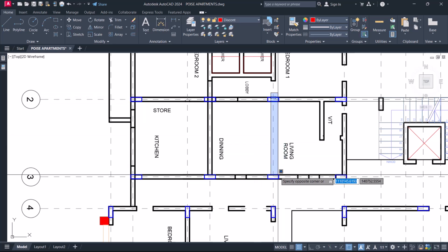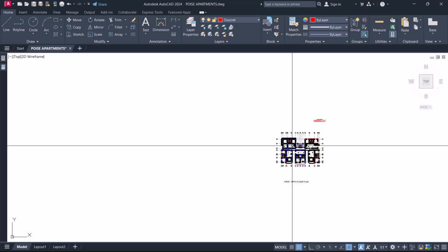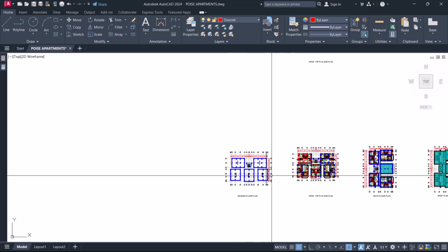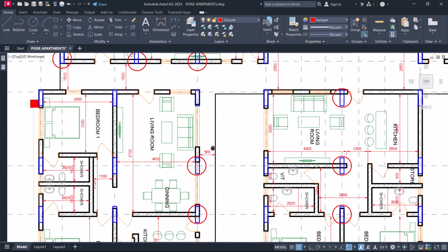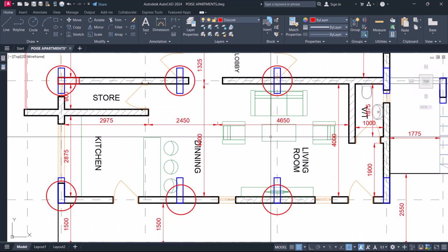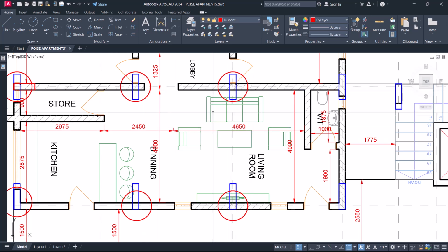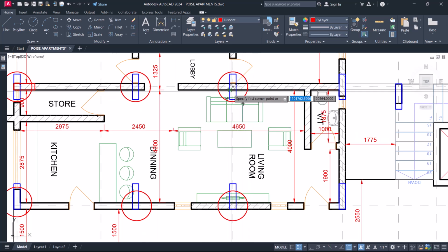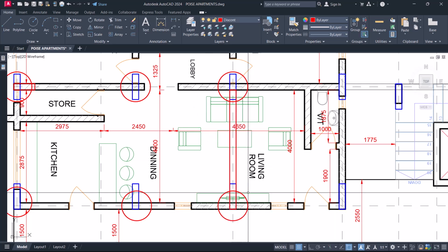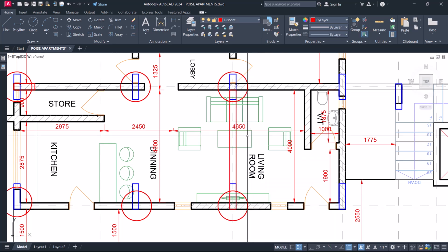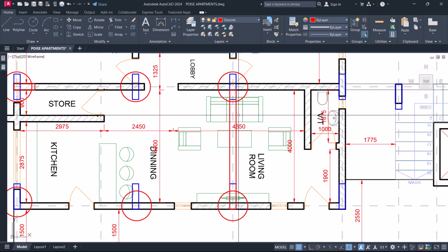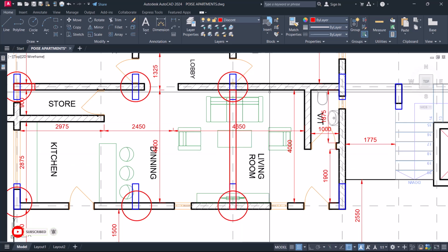because since it's a flat slab and we are not using a beam for these partitions, while they are actually sitting here, let's come down to that part here. So due to the fact that we are designing with a flat slab, this is advantageous. If we are using a beam for this point and they get to sit at this living room area, there will be a drop part of the beam. If we are using a 450 beam and we are using a 150 slab, there will be a 300 millimeter drop beam, and this will actually deface this living area.